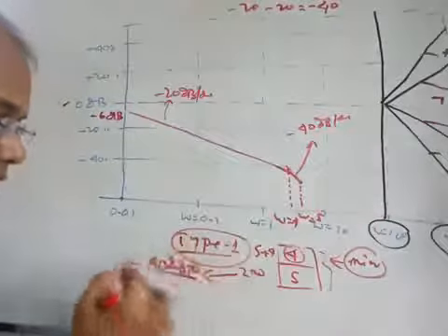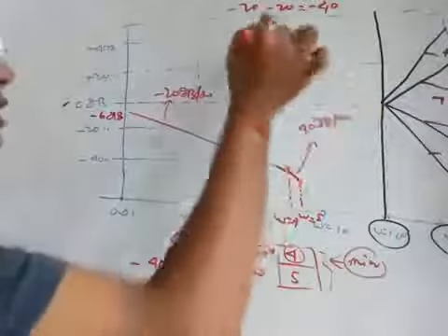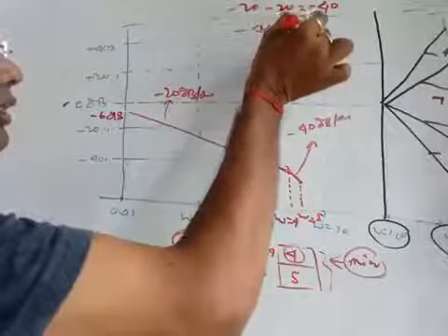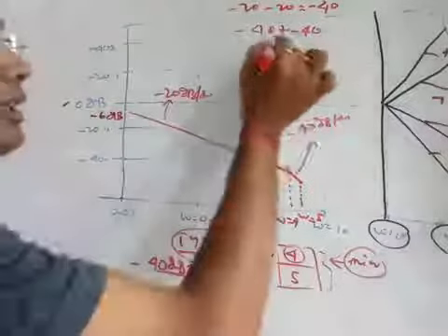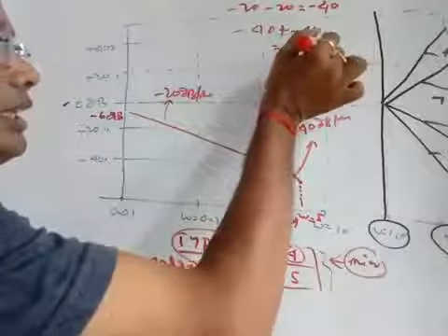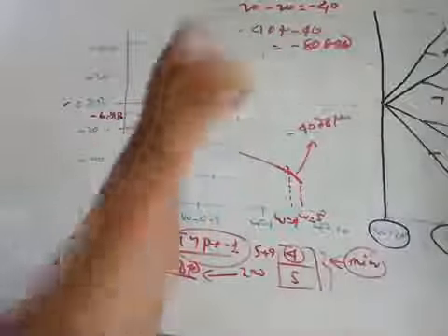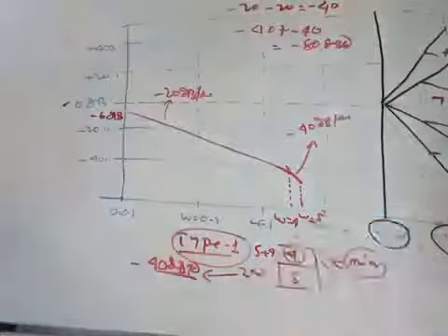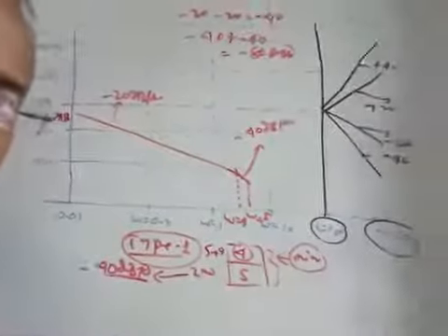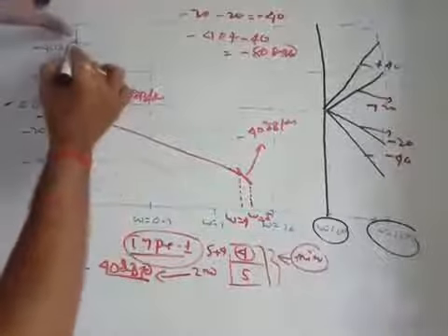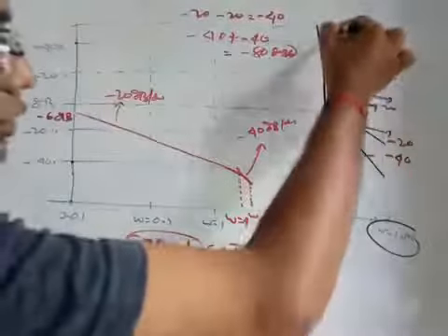Now here you see the slope is minus 40 dB. So minus 40 dB is your previous slope, plus minus 40 dB is your next contribution due to this second order factor. So what is the resultant slope? That is minus 80 dB per decade. So you need to draw a reference line which has minus 80 dB per decade slope. Minus 80 dB means 40 dB to minus 40 dB. So if a line is drawn from this magnitude,